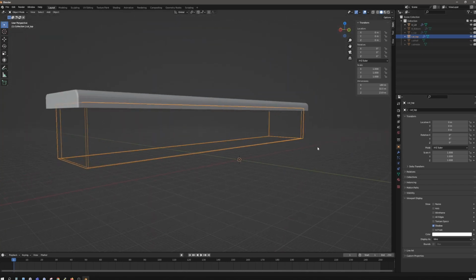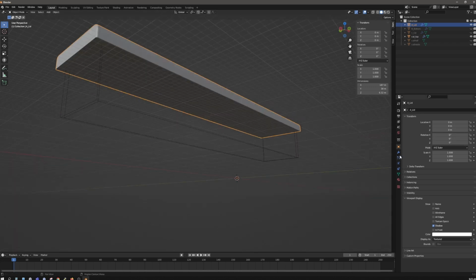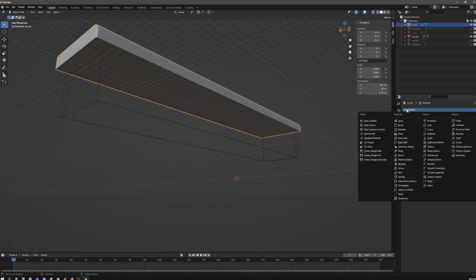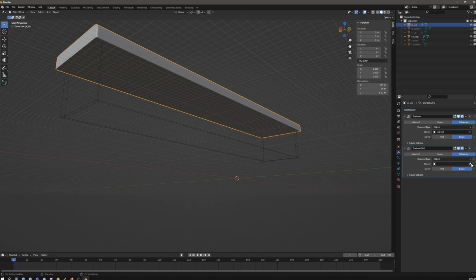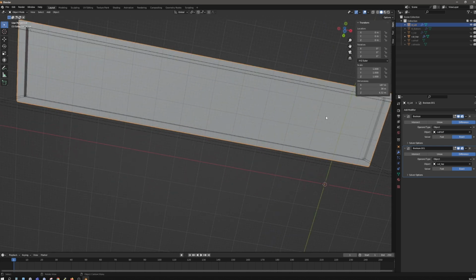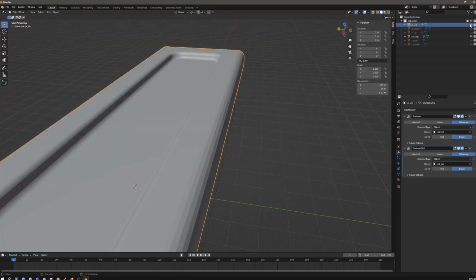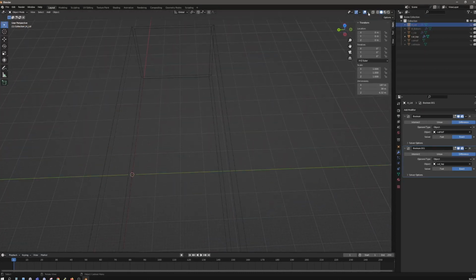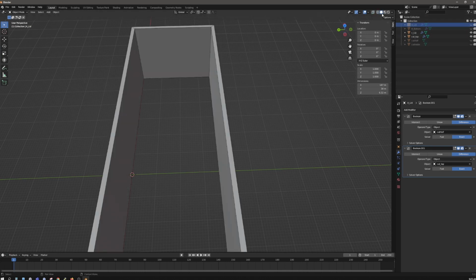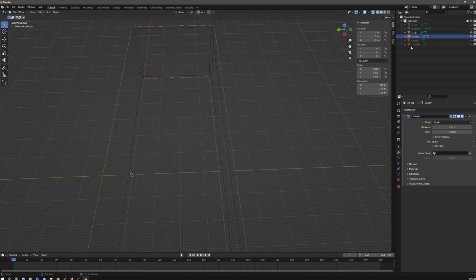And again, as you can see, this is all repetition. Select your object, go to your modifier tab, grab another Boolean, and then cut that object out. And look at that, we have a slot for that lip to go into. Now, something you definitely want to be aware of: let's turn that back on. Go to wireframe and turn our lip back on. I want to make sure I'm using my cut top selected. So try not to get too confused.